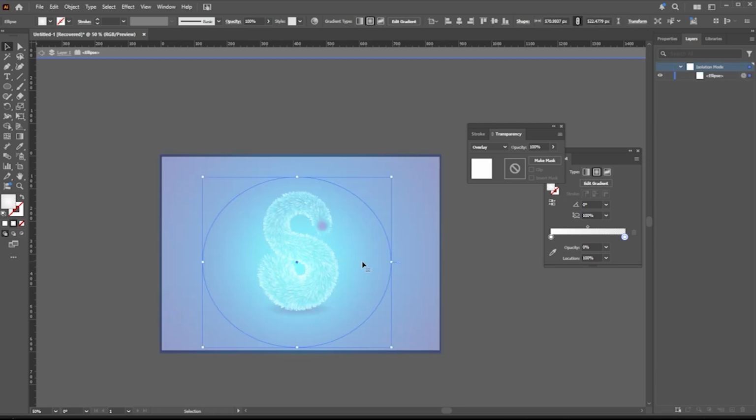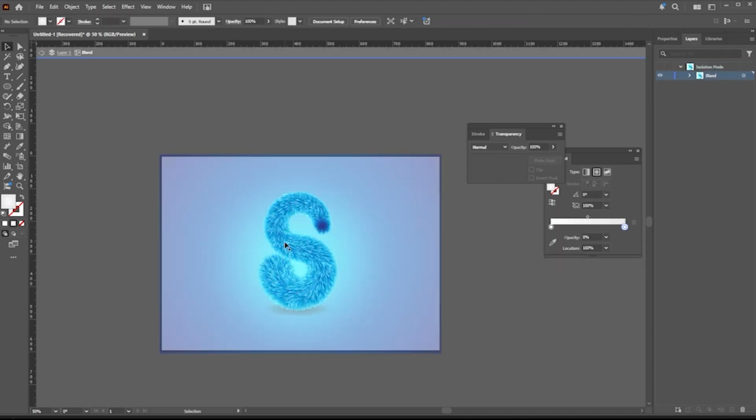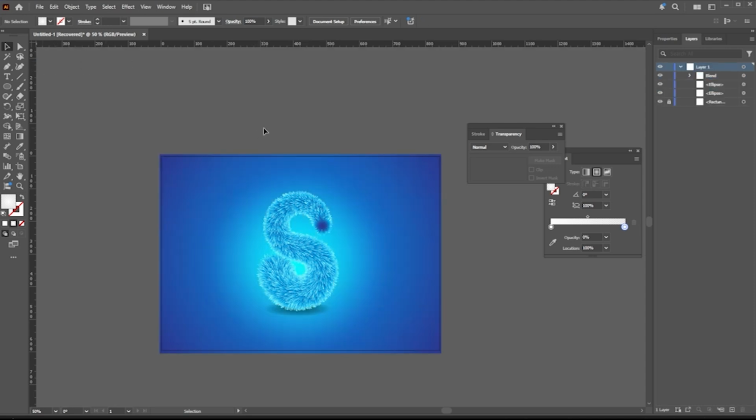Everyone, when you do it again, go ahead and click on this specific layer. This means it hides or disables all your other layers, keeping only the one you are working on active. You select. Then you can either click this arrow or double click to exit that mode. Exit, okay.